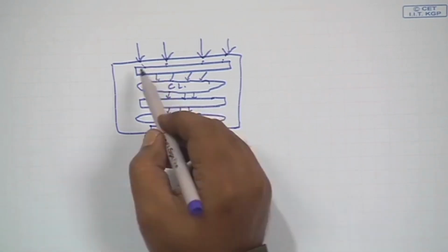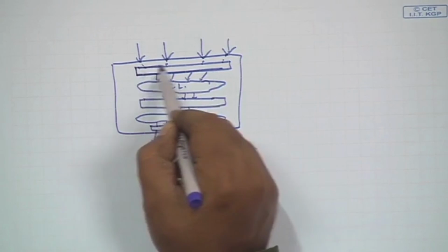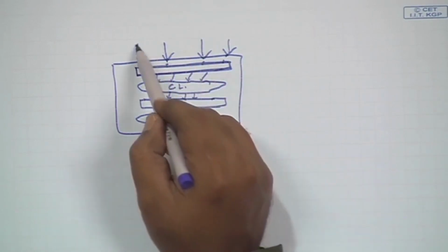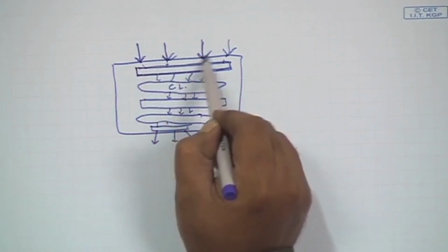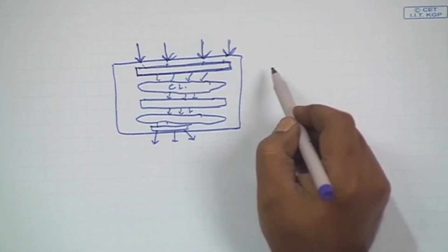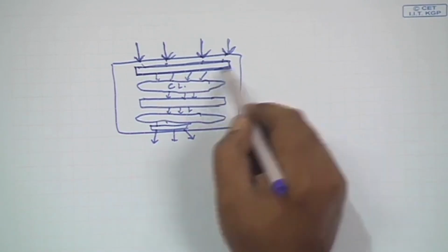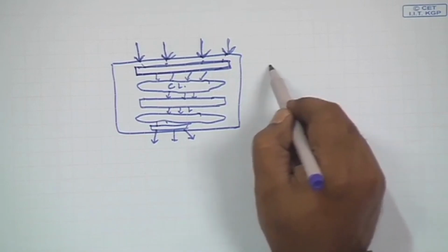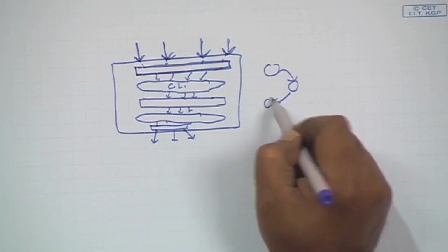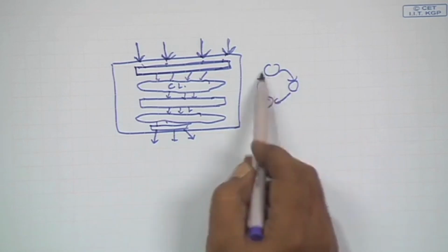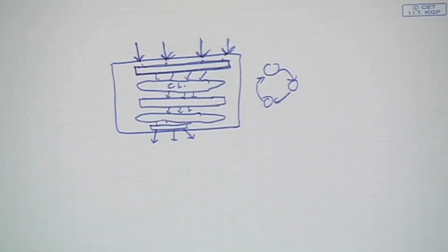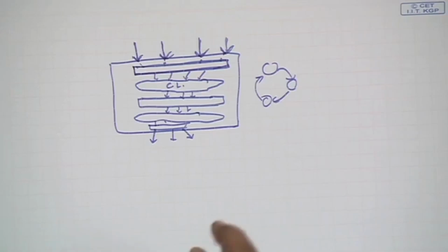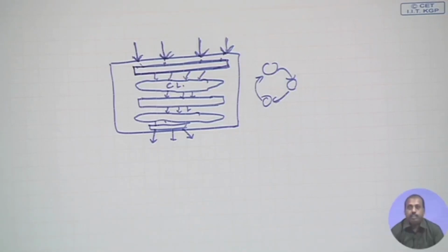So, these data path registers are normally controlled by the primary inputs coming from the outside world. On the other hand, for controlling all these registers, combinational logic, etc., the control part is implemented by means of some FSM, so that at various states it controls the data path elements. I may need to test a particular functionality, and as a result I need to put this FSM in a particular state for fault excitation.